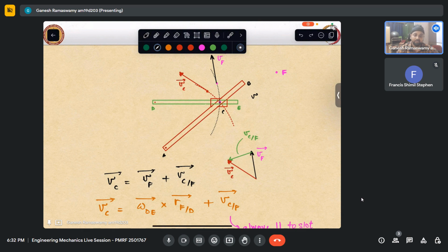Let us say that I was rotating with AB. Will I see V move anywhere? I will not see V move anywhere. There will be no relative motion because I'm rotating with AB. In such a case, its acceleration is known. It is having only centripetal acceleration. If it is rotating with some angular acceleration, then that tangential acceleration will also get added to its acceleration. Let us say this will have a centripetal acceleration like that, and let us say it is having a tangential acceleration like that. So eventually, the point C's actual absolute acceleration will be something like that in the most general case, either like that or like that, whatever be the case.